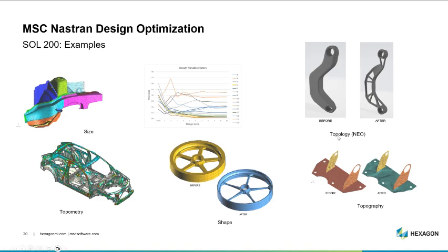And then we've got topology optimization, which traditionally, simply, I've got some kind of a space, I've got loads, and I want the software to tell me where material can safely be removed. Now, in the latest versions of Nastran, there's an additional option, the Neo solver specifically for this, and then it acts more like, if you know the product, generative design, where it'll end up with actually a smooth 3D printable shape or a part that you can mesh if you want to do a more detailed analysis afterwards.